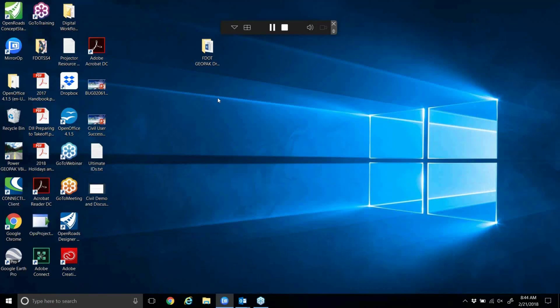And then another set of components we have here are areas. We have to designate a certain area. That area receives a certain amount of rain, and then that area times the depth of the rain that hits that area determines how much we have going through an inlet. So each inlet or each node is going to have its own area assigned. That's going to let us calculate how much flow we have through that node, and that's going to let us calculate the link sizes or the pipe sizes.